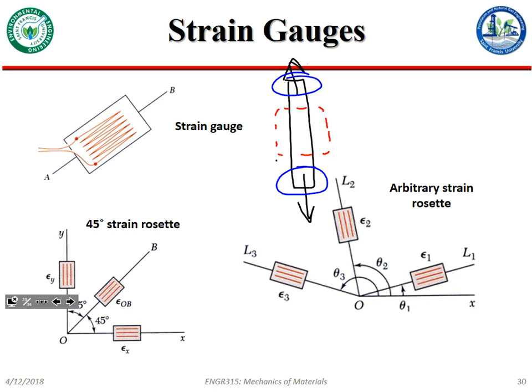That's where we start getting into the world of finite element models and computer simulations of materials. It's very difficult to do a hand computation and get the stress distribution near a load. You can do it after it's settled out to some average value, but it's difficult near some applied load. And we also said this is for a bar of uniform cross-section. If we vary that at all, we get all kinds of crazy stress distributions and concentrations.